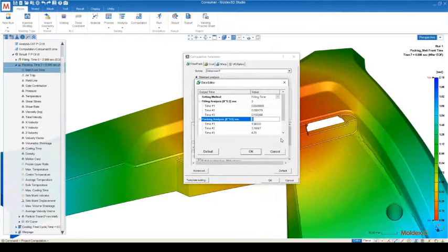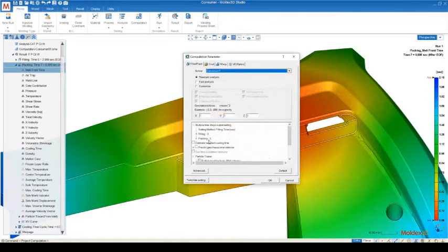The thing to be wary of is that the number of time steps that you use is going to impact your computation time slightly. Usually time steps take anywhere between 20 and 40 seconds to export. So if you were to use the maximum, which I believe is 99, it can add a significant amount of time to your simulation just because you're exporting these results so constantly. So you don't want to use too high. I usually use anywhere between 10 and 20. That would be my recommendation here. But you can see for this simulation, we only used 5, and that was not enough.